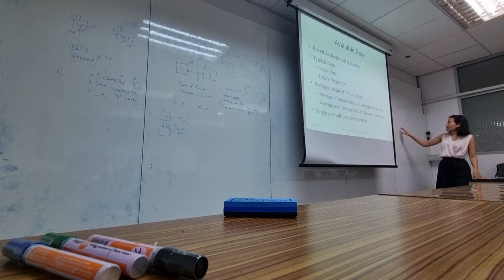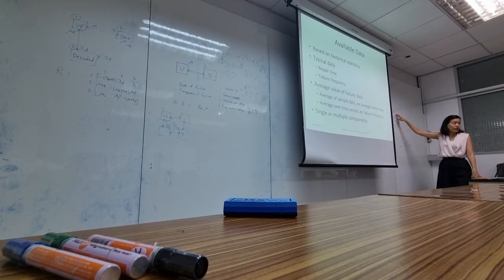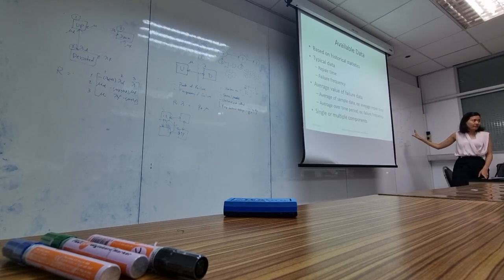So knowing the failure frequency, you can find the mean time between failure, right? Frequency is the reciprocal of that time. And knowing the time of the repair, then you can find the time to fail. And all of this information you can get. So with just two pieces of information, you can get everything. Okay? Failure rate, repair rate, probability, frequency.